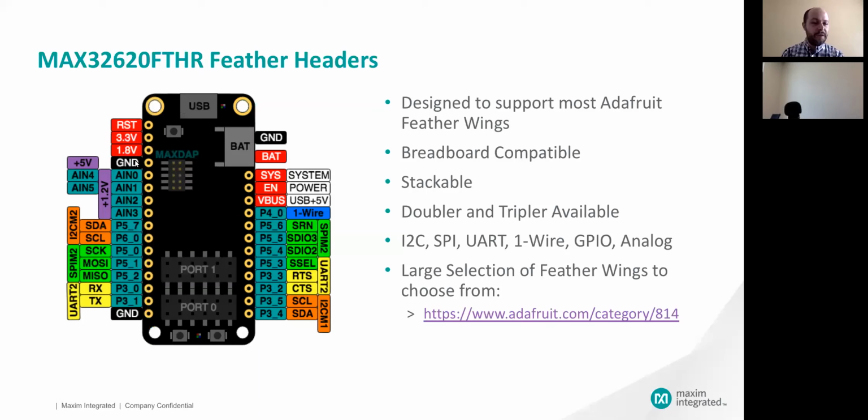One other thing to point out while I'm here on the analog inputs, we've got a 4-channel ADC. Those 4 channels, the full-scale range is about 1.2 volts typical, but the first 2, analog 0 and 1, have a programmable divider that allows actually measuring 5 volts directly on those pins. And when you want to use the divider, rather than setting a configuration register, because the Arduino and Mbed libraries don't support that, we just call them a different input. So you refer to it as analog input 4 or 5 if you want to use the 5-volt support.